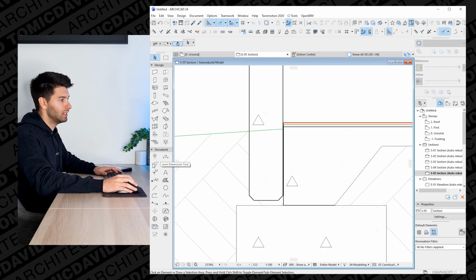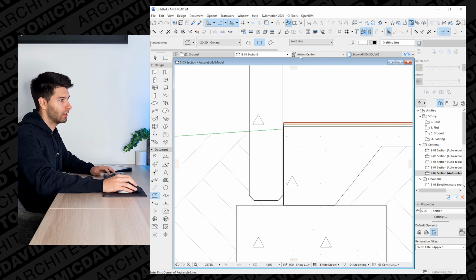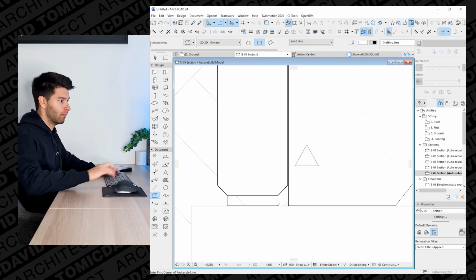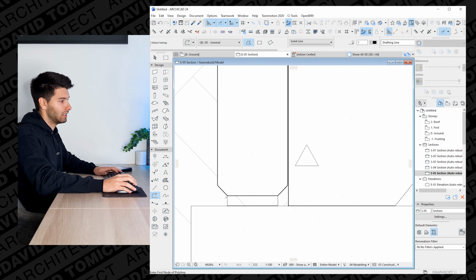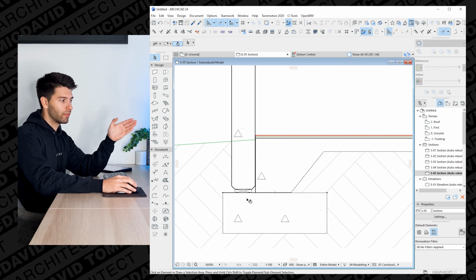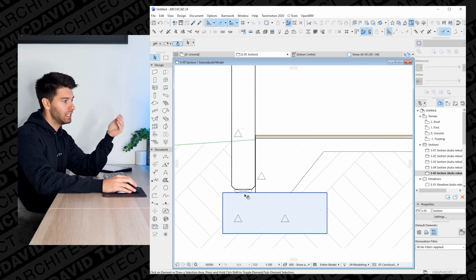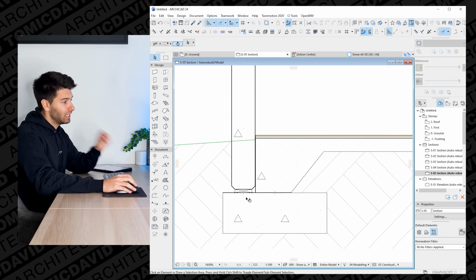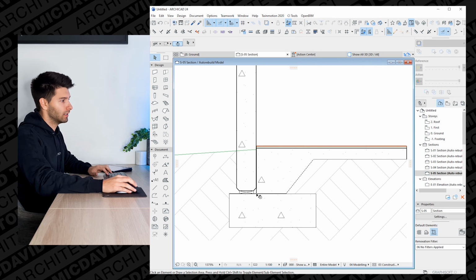So similar to what we did with the timber construction a minute ago, we're just going to draw a small box here, 130 by 25, and then we're going to draw an X through the middle of it. Now that concrete wall sits on top of a packer for stability and rigidity. Those packers will be about 1200 centers, depending on again what the engineer specifies in this instance.